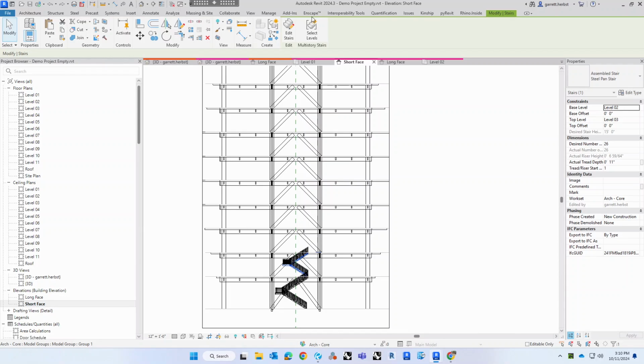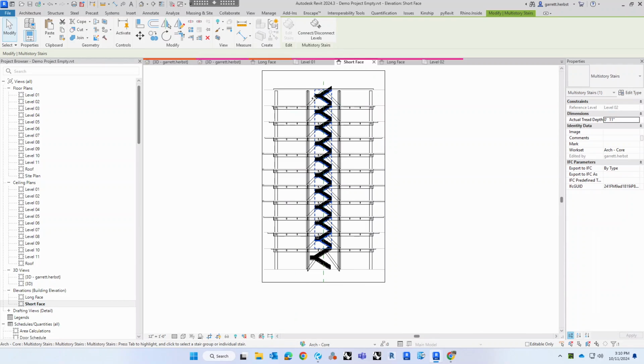So like I said, you need at least 2 stairs, especially in a high rise. And I think you guys are doing mid rise, but again, if not, that's fine. So I am just going to mirror again using my handy dandy center line. The reason why I'm doing it again, and depending on your project, you might not have to do this, but right now, predominantly the doors that are going into this stairwell are going to be on the south face for that stair.